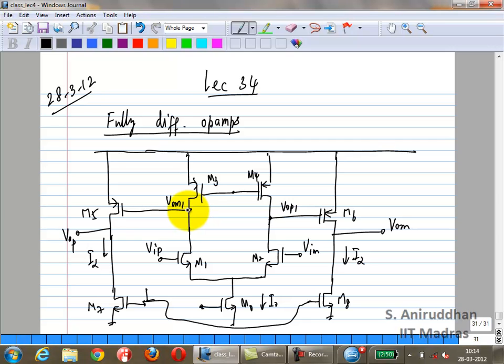Okay. What else? Yes, Milan. Gate of M3, M4 and M0. Again, it's the same thing. This is the same as a single stage op amp. So you can control either of these. Let's say I do it and I'm going to control this. That's good. So we know one way to set the common mode of the first stage.